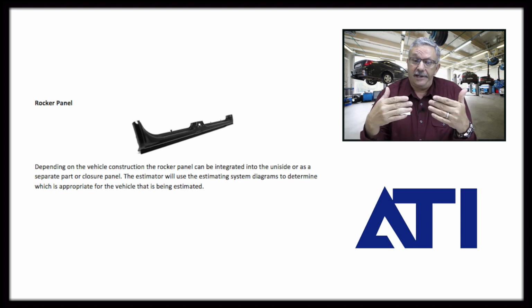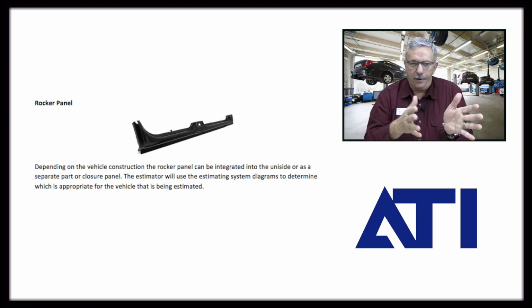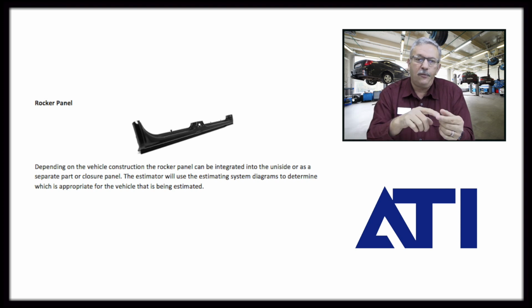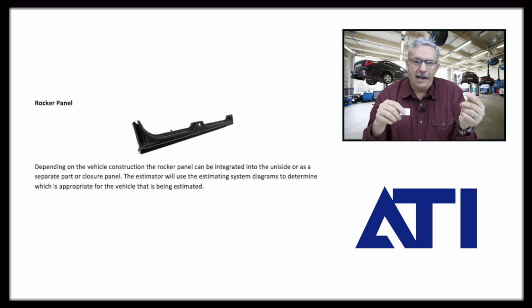What does that mean? Well, it's a whole process that we have to follow. It's a two-part epoxy or a two-part etch material that we use first. It's put in with a wand. So we've got to think about calculating that whenever we're putting these closed box welded panels on. Then we have to also install a refinish process to seal it. Now, the refinish process can be two things. It can either be paint, depending on the manufacturer, and they will specify, or it can be what's called a wax-based material, which is essentially a cavity wax.